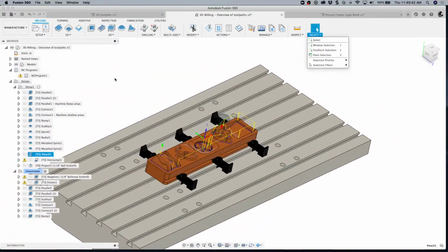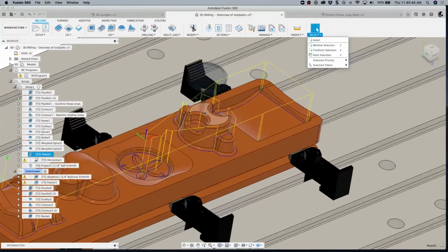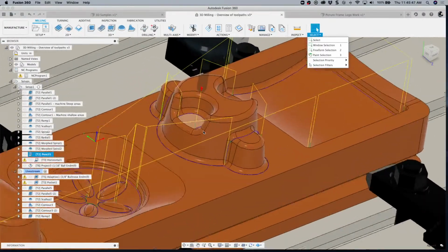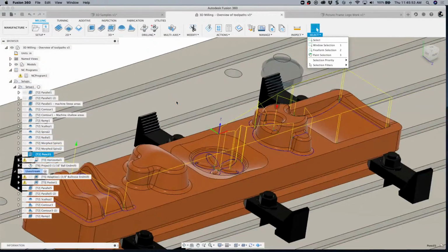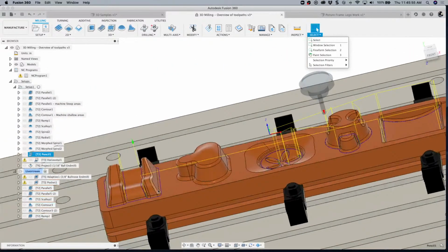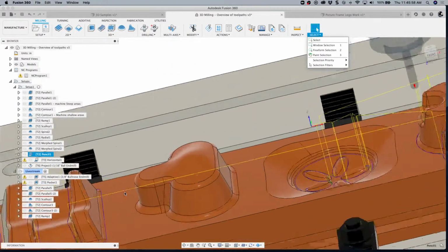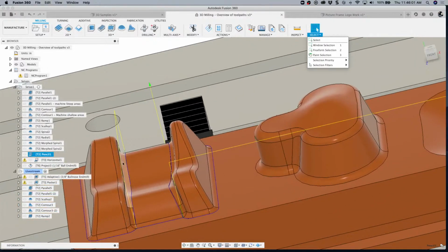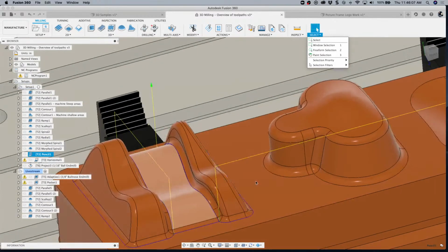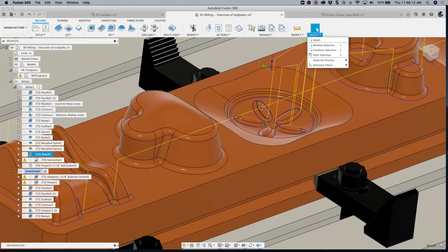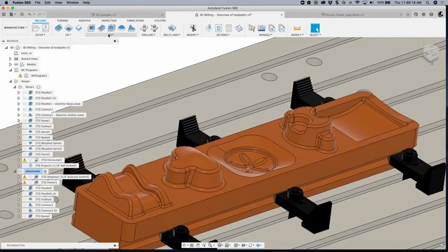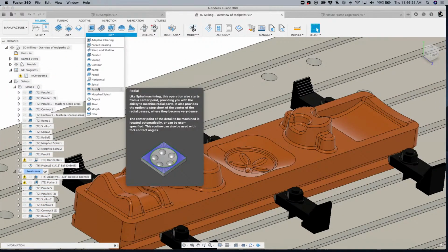All right. So what pencil will do is when you're roughing this, you'll come through and then select pencil, and it'll give it one nice contour. If you're doing mold making and things like that, you can really notice it. Because if you're doing a scallop here, and your tool is going left to right, you get, in my opinion, a kind of ugly toolpath when it hits these areas. Or even on this guy, sometimes, if you're going this way. And then what pencil will do is it'll clean it up nicely. Okay, so pencil, and I apologize for my selections not working.